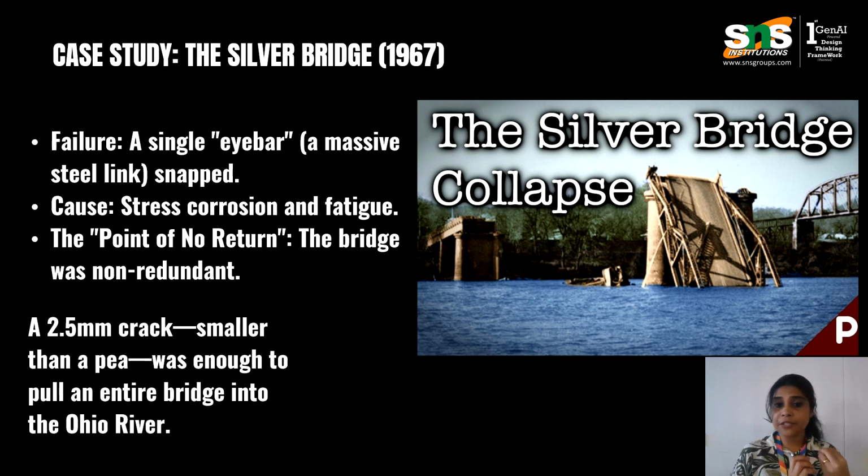Because of the way the bridge was built, there was no backup. When that one crack reached its critical size, the eye-bar snapped and the entire bridge fell in less than 20 seconds. It was a non-redundant design, meaning it had no plan B.